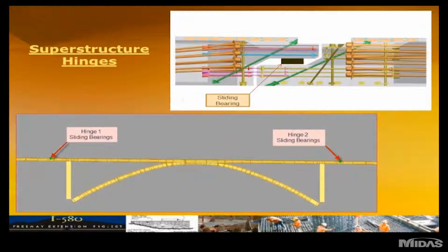We're going to go back to the hinges. This is the superstructure hinges that I mentioned before, and the locations are shown on the bottom. So as you can see on the top schematic, the geometry control for casting the central portions of the upper and lower hinge where the bearing sits, as you can see, requires a high degree of geometry control.